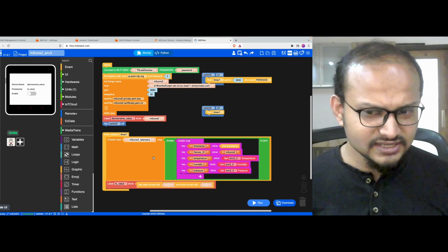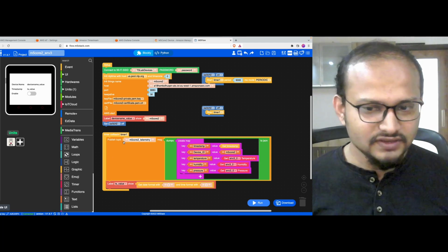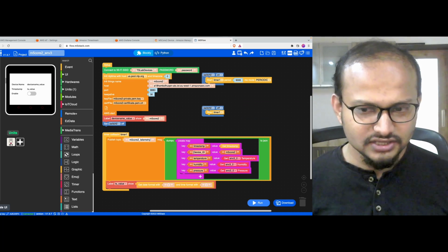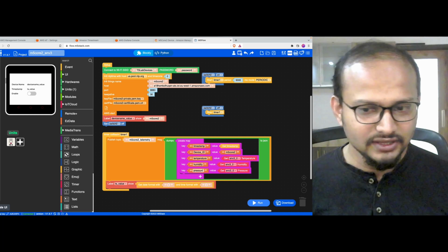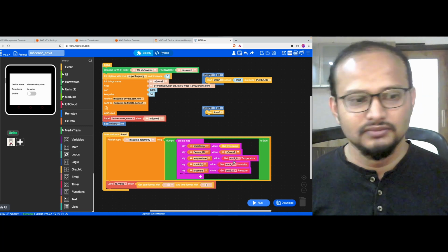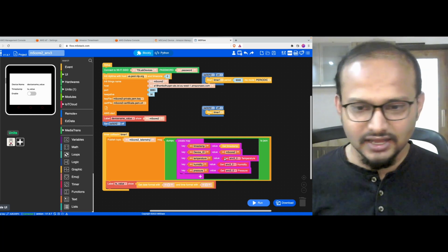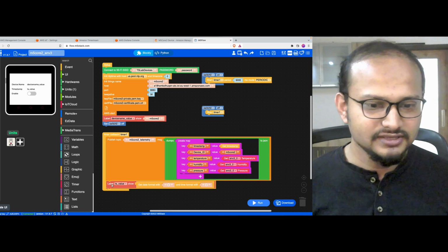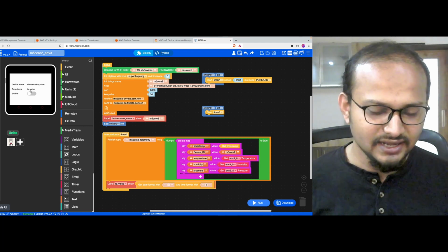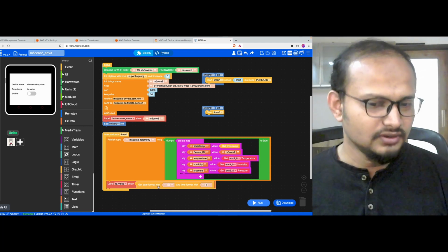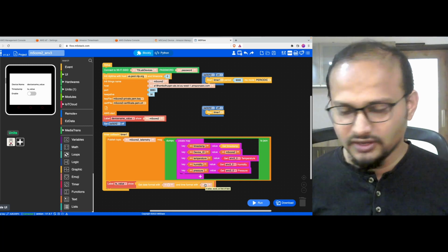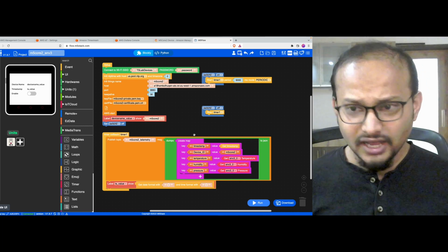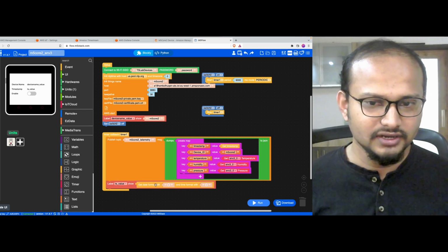In this topic, what does it publish? It creates a JSON which has all these values: timestamp, device ID, and temperature, humidity, and pressure. Those are the keys and the values for them. We are getting it from the ENV3 device. And then after it does that, there is also a TS value label on the display where we are setting the date and time in this particular format. Okay, so that's what this is going to do. We have pretty much configured this program.